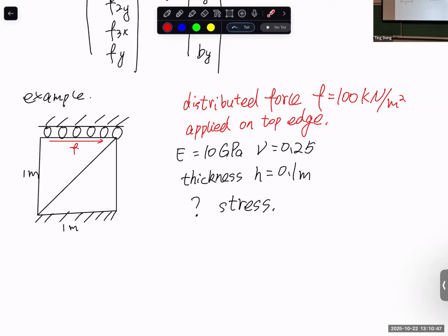But we have 2 nodes, two nodes at a fixed distance. But still there are 2 nodes. You cannot really say they are at a fixed distance, because all the structures in our undergrad solid mechanics are deformable structures, not rigid bodies. The deformation may not be super large, but with metal and an applied force, since we're calculating strain and stress, there is relative displacement between these 2 nodes. Okay, yes, it should be 2.